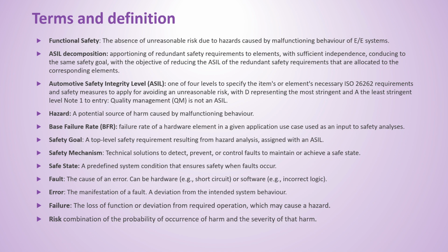Okay, so if the car's computer glitches, it shouldn't cause harm. What's a hazard then in this context? A hazard is simply a potential source of that harm caused by the malfunction. Now, there's a key sequence to understand. Fault, error, failure. Okay, like dominoes. Sort of. A fault is the root cause. Think a tiny defect in a sensor, maybe a software bug, a short circuit.